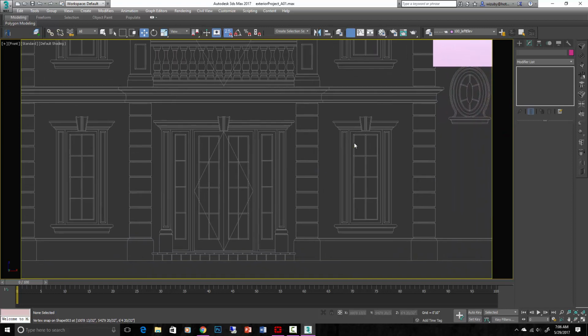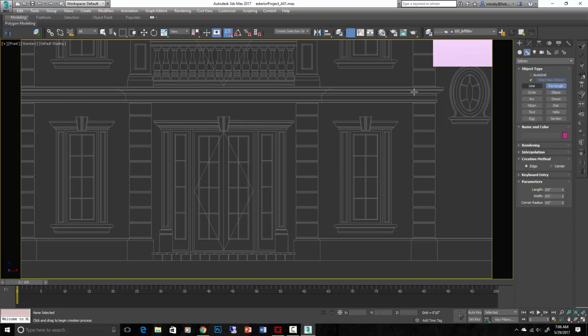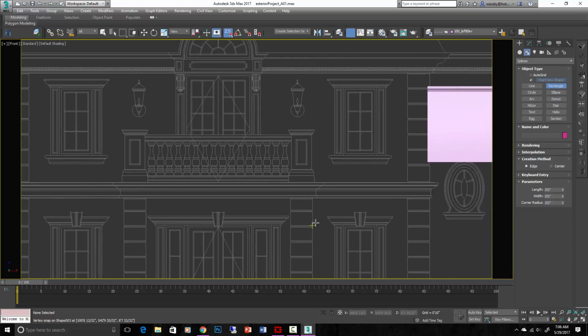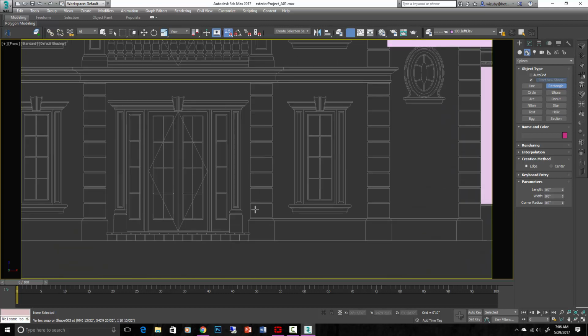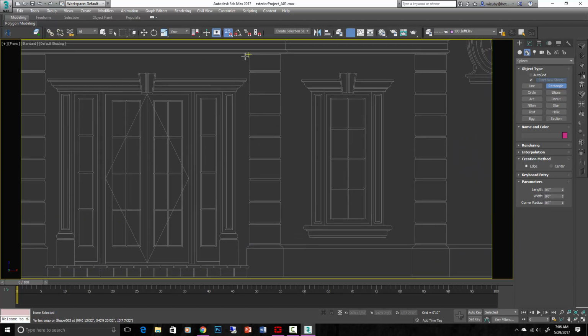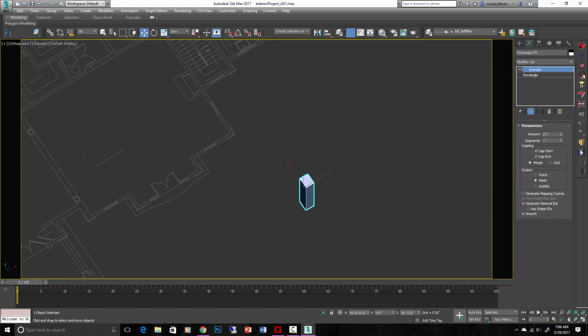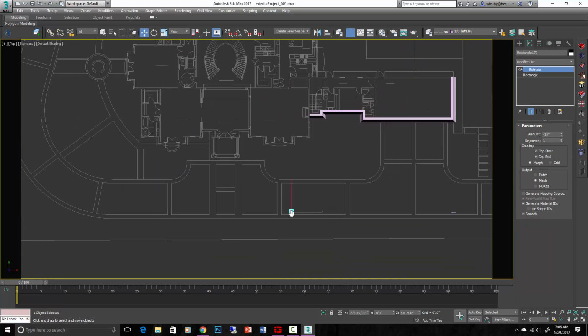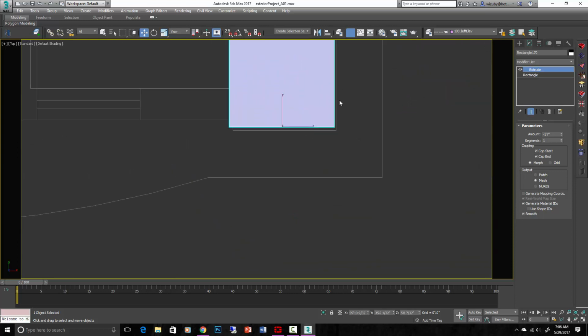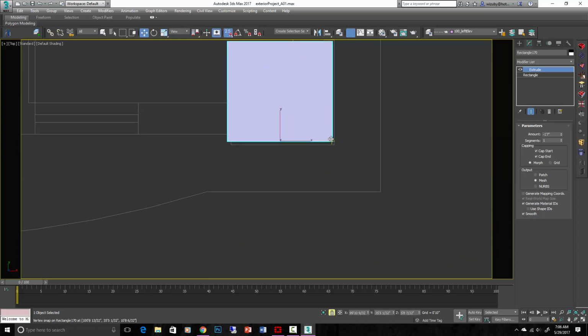I've showed you a little bit of poly modeling too. Let's take a few more things in this scene and model them, and then the rest are going to be on your own, but it's going to use all the same tools that I've been showing in this video. Okay, here's some edit poly tips for modeling this column right here. Let's take this and just start with a rectangle. Okay, go to the top view and we'll extrude that rectangle. Make the basic shape for that. Put it in place. You can see where it's going to line up right here.